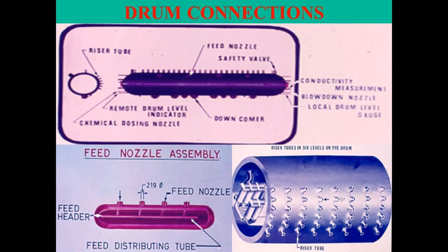We have connecting tubes for superheating, and side by side we have a sampling arrangement, remote liquid level indicator connecting arrangements, chemical dosing lines, and along with that various connections for pressure and temperature measurements. All these connections are found as mountings and attachments within the system.